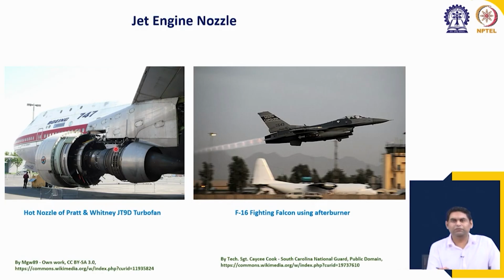So, the combustion products come at relatively high pressure after the turbine, and at high temperature. So, there is a lot of energy in the combustion products, and these combustion products can be taken to low pressure, so they can be accelerated in the nozzle and the exhaust gases will come out at high speed. Okay. So, this has a converging area. Typical nozzles that we know of have converging area; these are known as convergent nozzles.